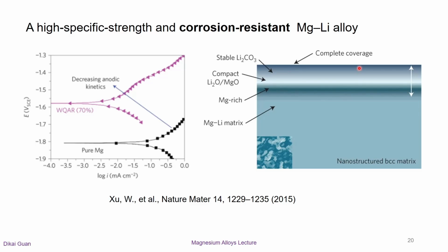The small and finely dispersed lithium-rich zones promote the formation of the protective lithium carbonate film, and the absence of relatively coarse second phases or intermetallic particles prevents conditions that typically degrade alloy corrosion resistance resulting from microgalvanic interactions between the particles and the matrix.